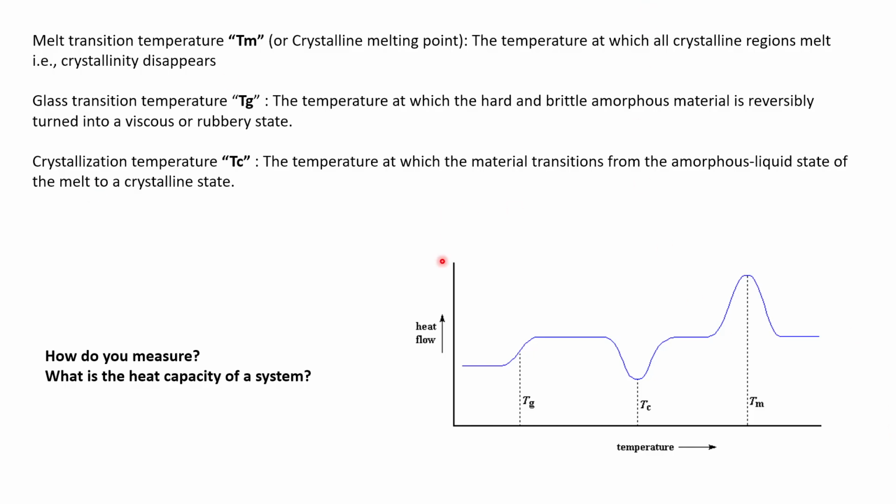And if you guys remember, this is what a typical graph for a polymer, or most polymers, looks like, where as you constantly keep increasing the temperature, first we hit the glass transition temperature, where if the polymer is crystalline, the crystallinity starts to disappear, right? So as you keep on increasing the temperature, the crystallinity starts to disappear, and the polymer becomes amorphous to an extent.